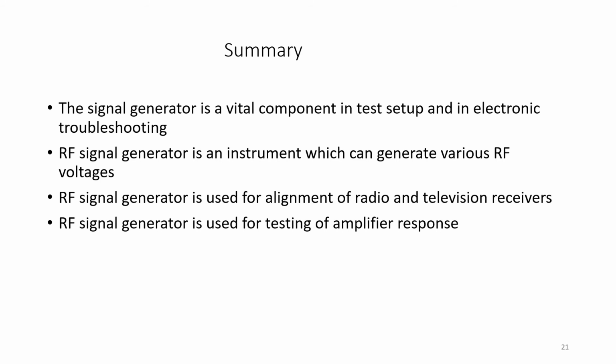Usually the shield is made with copper or aluminum and is fixed over the chassis. Mainly the shielding is used to prevent RF interference between the components, each block of the RF signal generator, to prevent emission of RF energy from any point except the output terminals, and to prevent RF emission on the power line. RF chokes and capacitors are used.